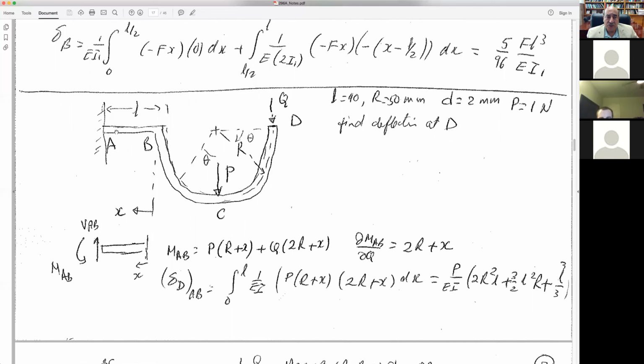So we have to divide it into one straight section, AB, and then another quarter circle from B to C, and another quarter circle from C to D. Now we notice right away that from C to D, there is effectively no force, even though there is a Q, but the Q is zero. So that part is kind of limp. It's not tense, so it doesn't have elastic energy stored in it. So we can pretty much ignore that part. The elastic energy will be stored in this section and in this section. So the problem is now simplified.